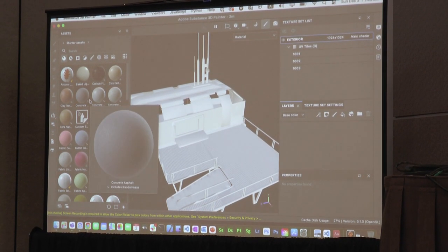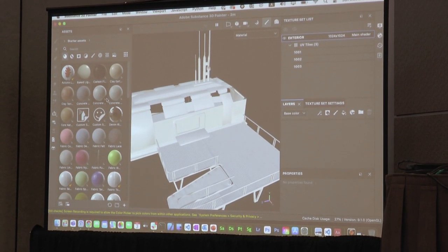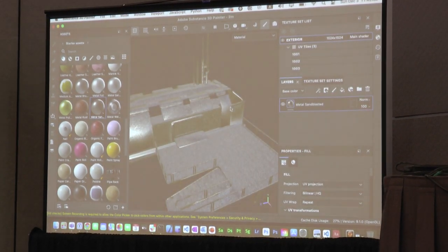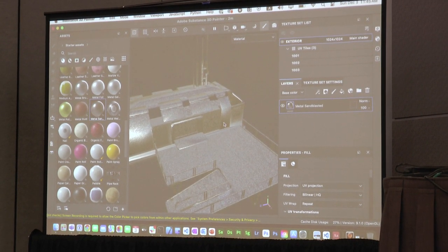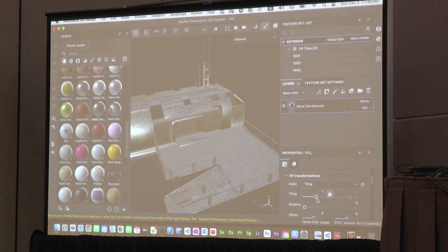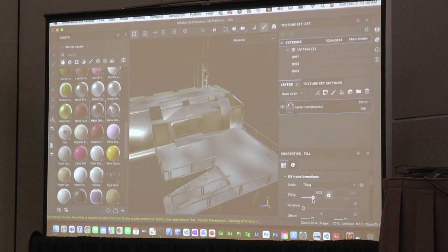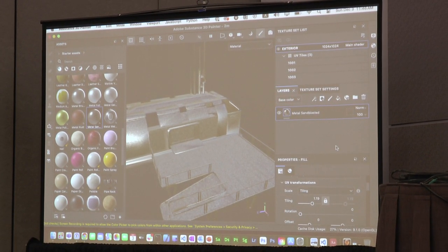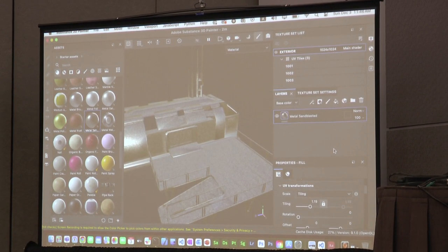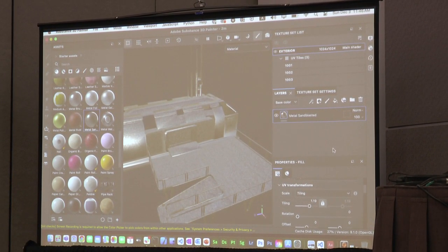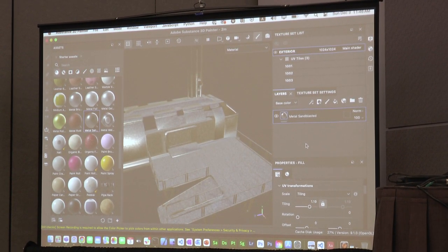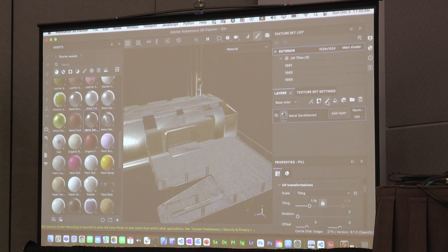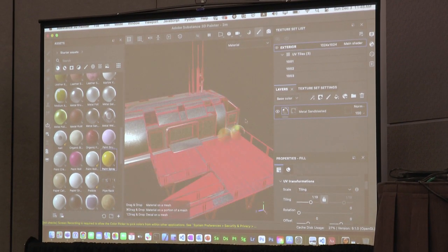On the left here, we have a bunch of starter materials, and we can select some material to throw in as a background layer. I just click and drag, and bam. Now we have a material, something to start with. We can adjust some of its alignment properties, some of its styling. This is more fine-grained, this is more coarse-grained. To get the look that you want, you'll have to deep dive into details about how the textures are mapped to the surface, but Painter gives you at least some visual idea here. And it is your old friend, the layer stack, which means we can create different layers of different materials. For example, we can just drag another material on top of that.